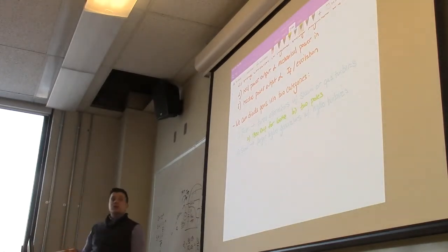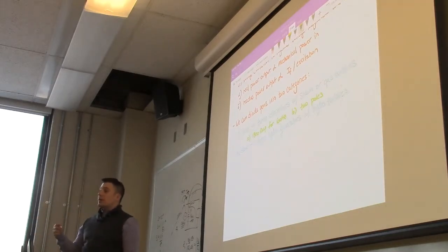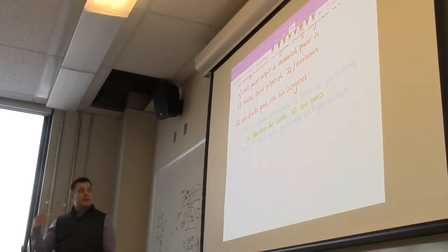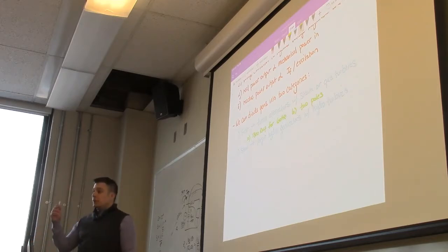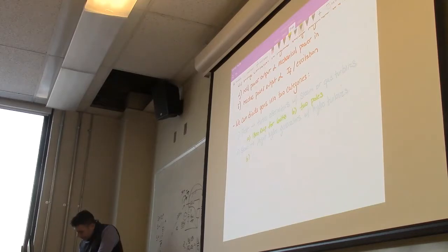And that's used for the slow moving generators for when the actual rotation is much slower than the 60 hertz, right? When you rotate at the 1800 RPM with the 2-pole machine, you generate 60 hertz. So for the slow moving, we have less than 1800 RPM.